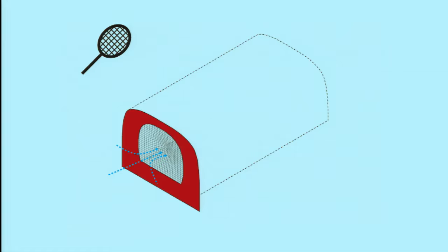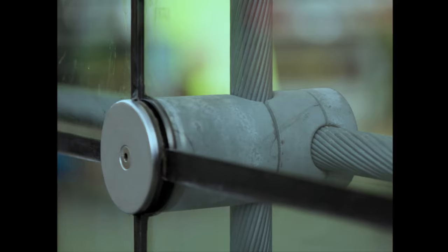So if a heavy storm hits the building, which we have also in the Netherlands, then in the center the facade can actually be pushed into the building by a meter, which is about this, so it's really a lot. Afterwards it's all soggy, so you have to open hatches and you need to put back the pressure. This is one of these screws, as you can see here, that holds the 4 glass panels and the silicon.